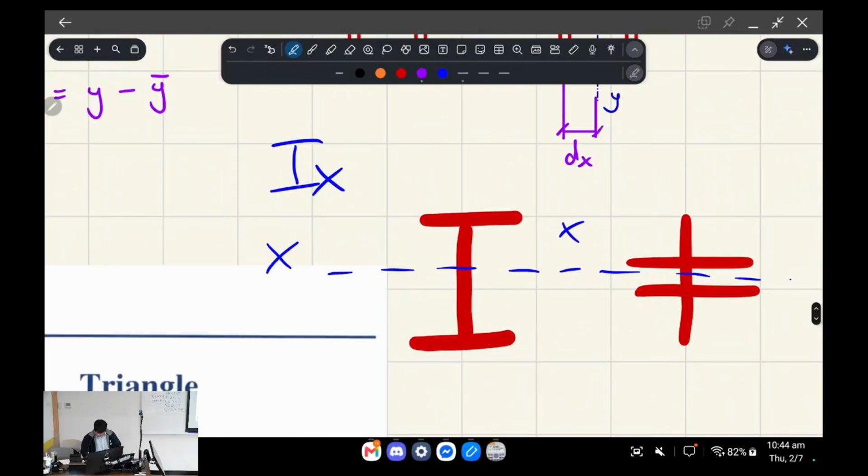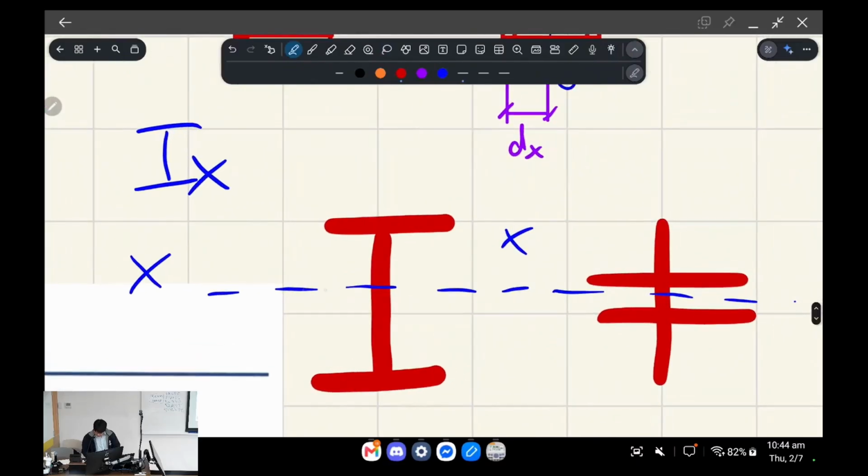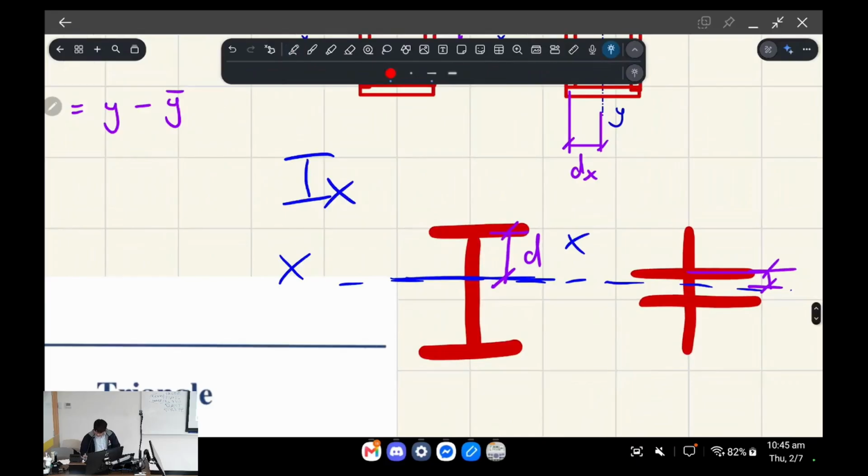The idea is that you have these three rectangles, right, which contribute some amount of stiffness. However, whenever one of these rectangles doesn't lie directly on this line, we have to apply a formula which adds additional stiffness based on how far it's shifted, perpendicular to this axis. So this is the concept of parallel axis theorem shifting. And so what I'm trying to say is that because this rectangle, for example, has only shifted a little bit away from the bending axis, right, it's going to contribute less stiffness than this shape.